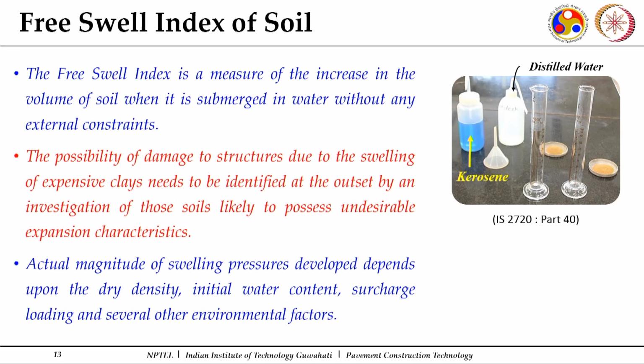Now another important thing is the free swell index, which gives an idea how much the soil can swell in the presence of water. This swelling will depend upon different factors: it will depend upon your gradation, and on the actual magnitude of swelling pressures developed. And if there is a swelling soil, you have put some layer over it.